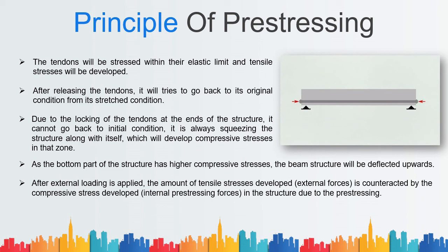After external loading is applied, the amount of tensile stresses developed, which is the external forces, is counteracted by the compressive stress developed, which is the internal prestressing force in the structure due to the prestressing. Therefore, the whole structure will become compressive and no tensile stresses remain in the structure.